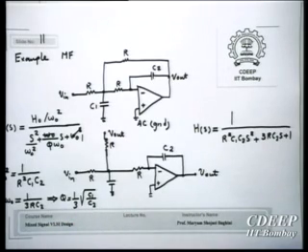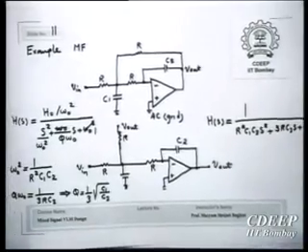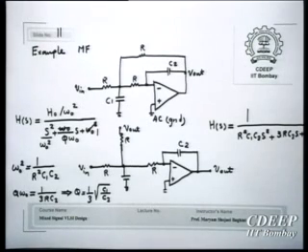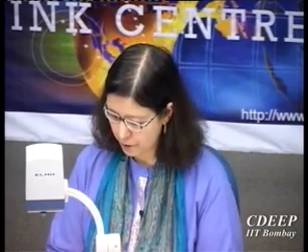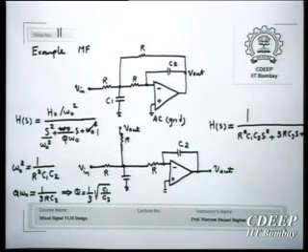So now you can see a little how these properties of multiple feedback help. For example, look at Q. Q is dependent on ratio of two capacitors. And usually on cheap implementations, capacitors change in the same manner and in the same direction with each other, specifically if they are not far. And this is a real case. Therefore, Q of filter can be kept almost independent of process variations and can be controlled by ratio of capacitors. And therefore, if you keep ratio of capacitors some constant, your omega 0 will be controlled by RC, just as one RC.